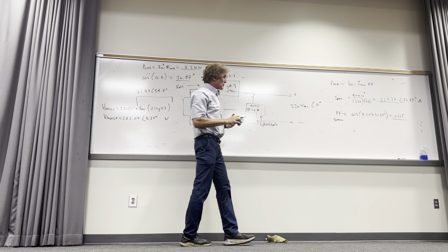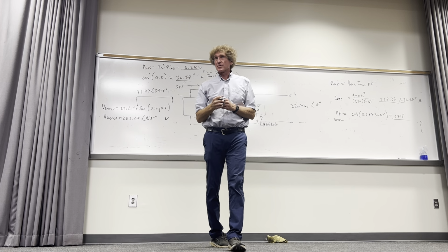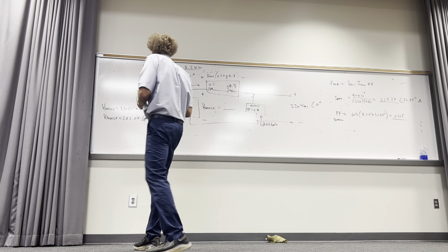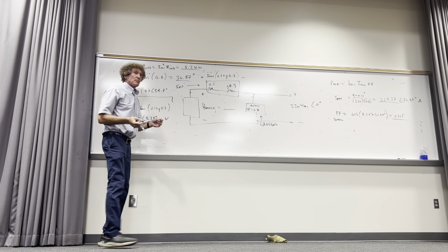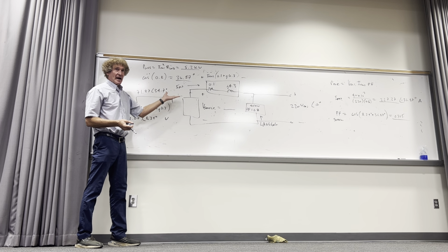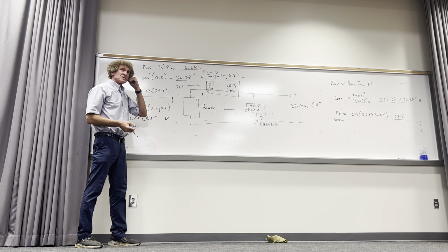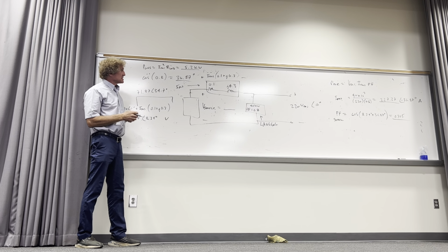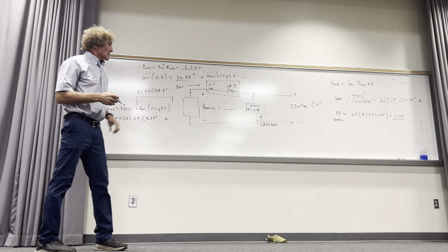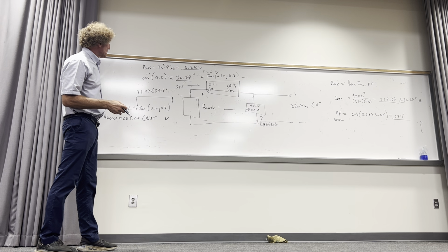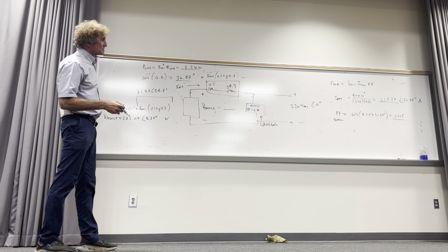All right, so we had 40 kilowatts that we're using, but we had to have an additional 5.2 kilowatts from the source. We were actually providing an additional amount, which means you're getting some loss there. Well, the power factor was 0.705.